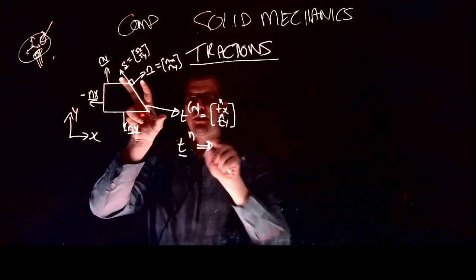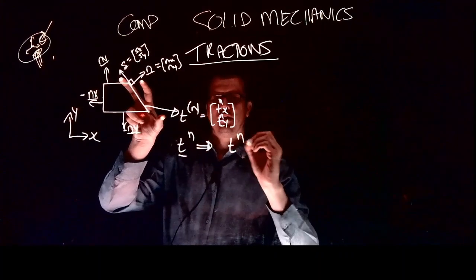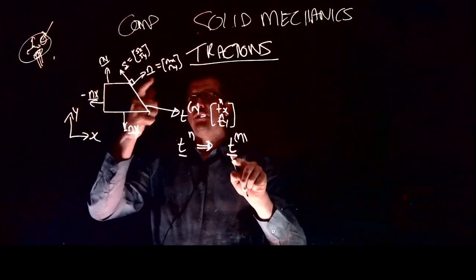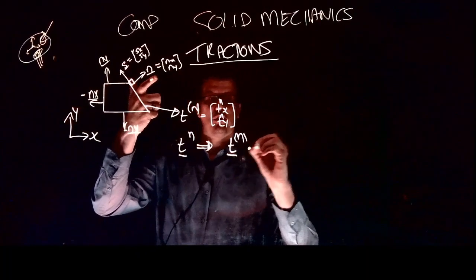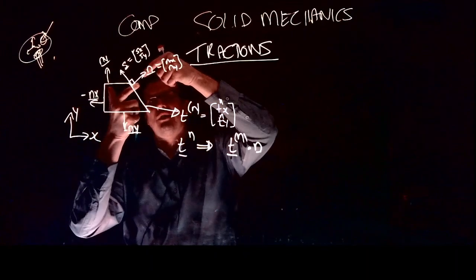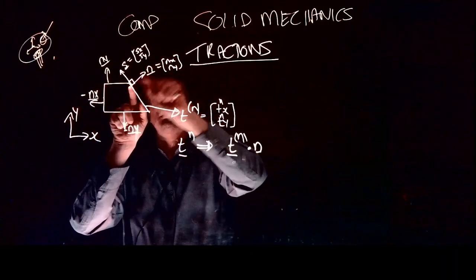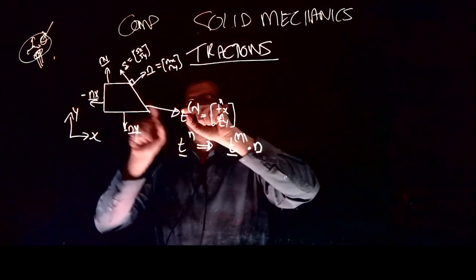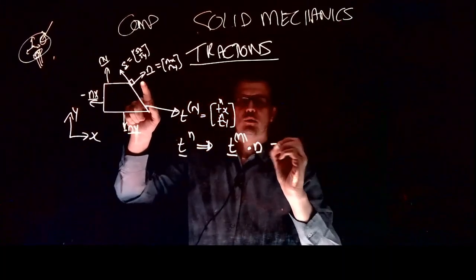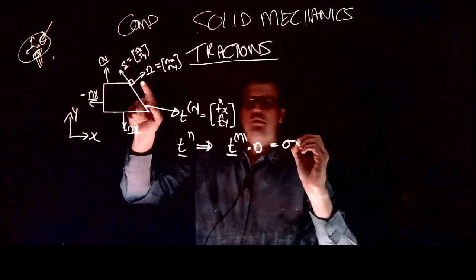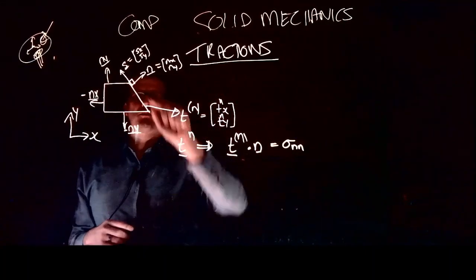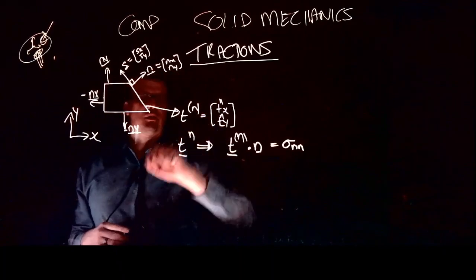So essentially, if I take this traction, n, which is now this vector, and I dot it with n. So what I'm doing is I'm taking this vector and I'm projecting it on there, and then I'm seeing how long along this n I have to walk to get this length of this vector. Okay, so I'm just dotting it with that, and then we'll call that essentially sigma. Let's call it nn. Okay, which is now the sigma component related to this n direction.